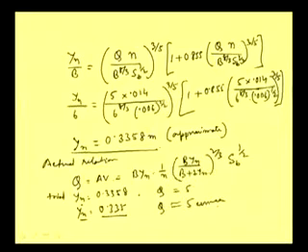And once we get this yn, say 0.335, what can be the actual size of the channel? This we can increase by some percentage, which we call freeboard, and then we can say that if our channel is greater than that value, then there will not be flooding. Well, that finer detail we will go into later, but this is the procedure.